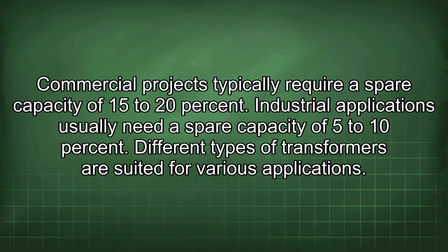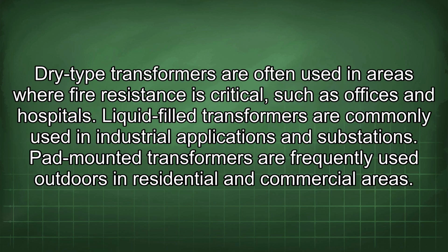Different types of transformers are suited for various applications. Dry-type transformers are often used in areas where fire resistance is critical, such as offices and hospitals. Liquid-filled transformers are commonly used in industrial applications and substations. Pad-mounted transformers are frequently used outdoors in residential and commercial areas.